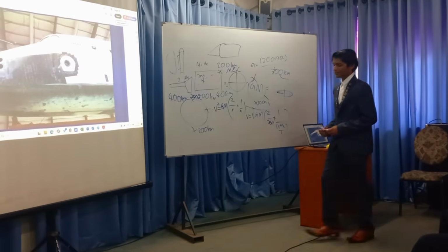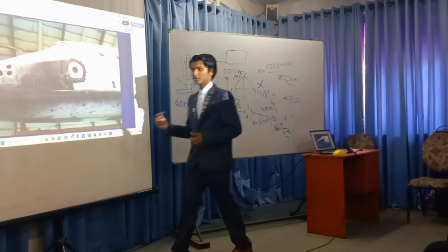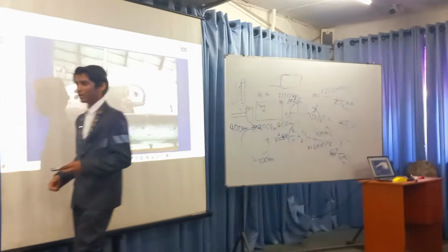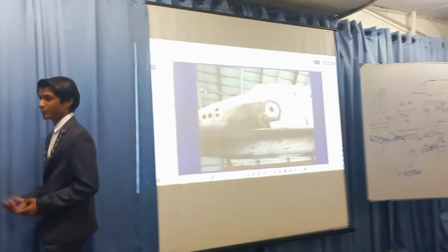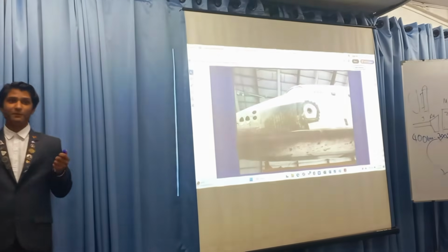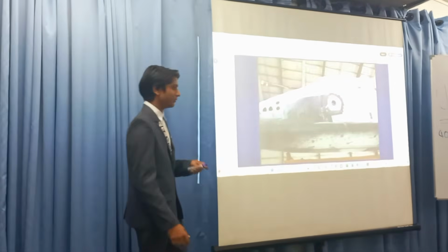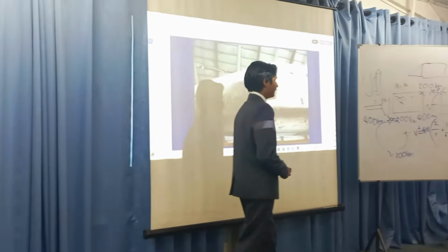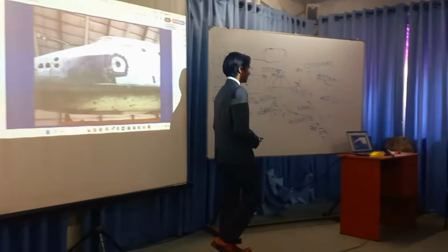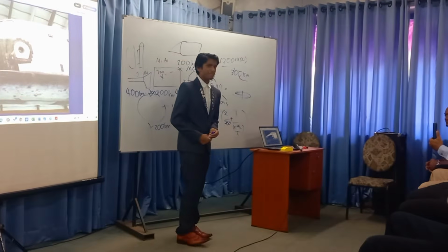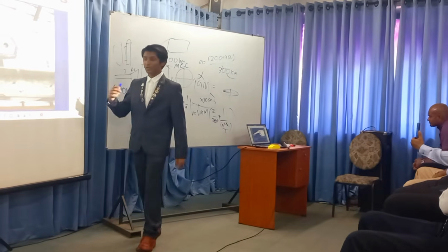The RCS are designed for constant adjustments. So the RCS engines could be fired on and off multiple times a minute. So you could fire an RCS engine about 50 times on and off per minute, and it will hopefully not be damaged. If you did that to any other typical rocket engine, like a liquid fuel rocket engine with hydrogen and oxygen per se, the rocket engine would likely collapse.